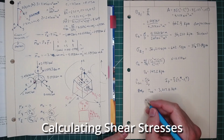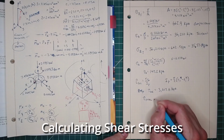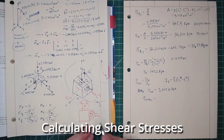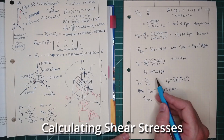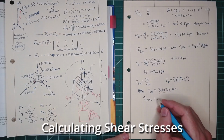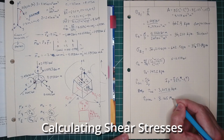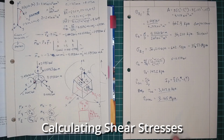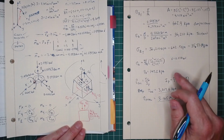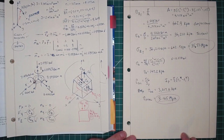Again, we need to combine these two. So we're going to get our total shear stress, tau total. In this case, both of those shear stresses are going in the same direction, so we can add these together. We add this one and this one, and we end up with 3.165 megapascals for our solution. Now that we have our axial force and our total shear stress, we can apply it to our in-plane stress.